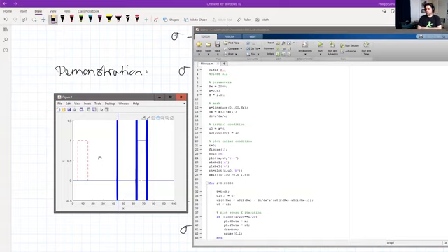So from a numerical point of view, if you want to integrate this equation, the advection equation, in a code, it's absolutely necessary to have this amplification factor below 1. Otherwise, it will just explode, as you have seen here.